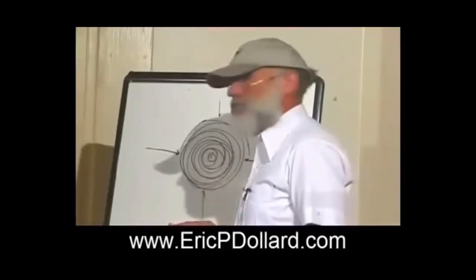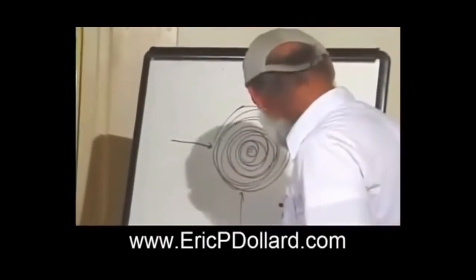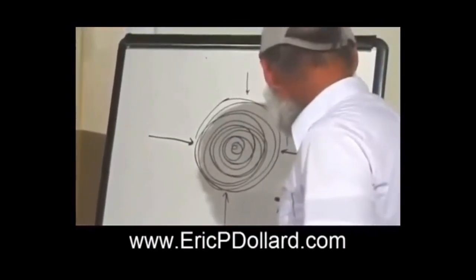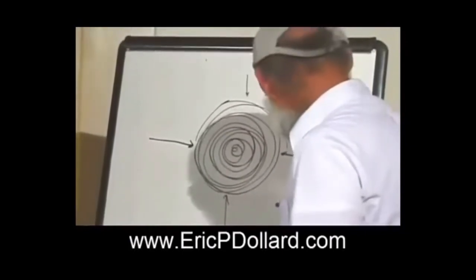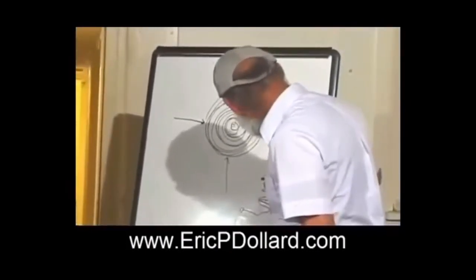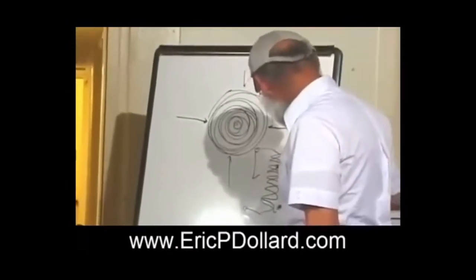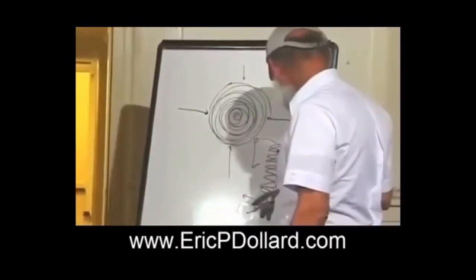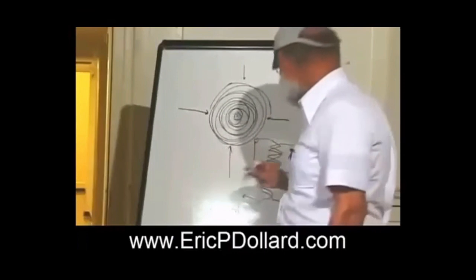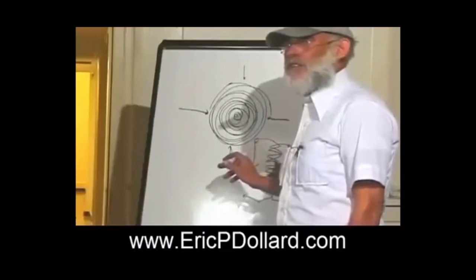There's no space variation. So I did some experiments, because Van Tassel was always talking about caduceus coils. That's a coil where you've got turns one way, and then compounded on it are turns the other way. What I found is, if this is coil A, I might have it wrong, but from the outside it'll look right, and this is coil B. If I connect them in this way at these terminals, this thing will resonate in an inductance-capacitance oscillation, but the amount of capacitance and inductance here is all screwed up by the fact the turns are wound backwards on each other.